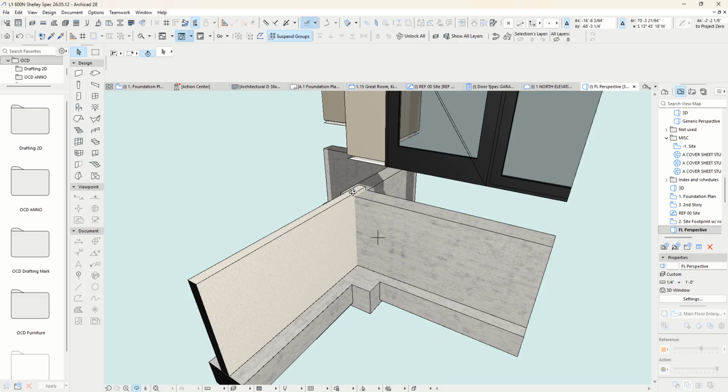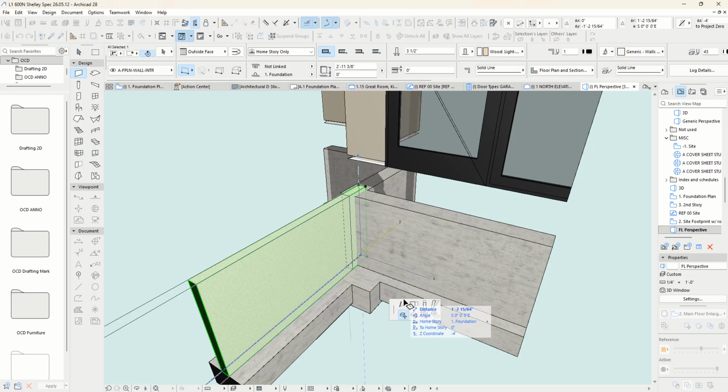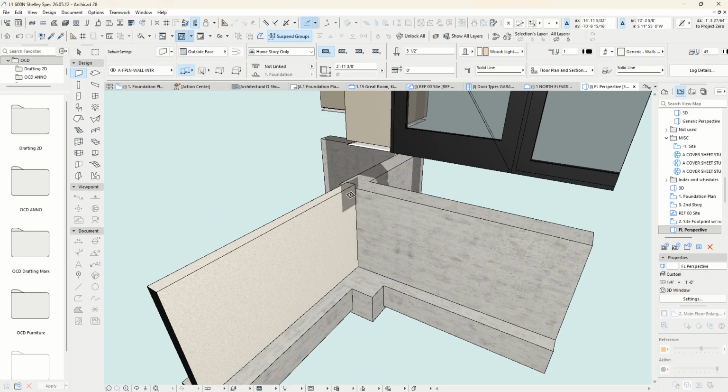But it's just the thing with walls. Sometimes they want to take on their own life and stop where they want to stop and start where they want to start. And it can be challenging. You can use priorities, which sometimes works. A lot of times it doesn't. But moving that back, maybe I'll move it back a 16th of an inch so it just doesn't interfere with that, because this is an interior pony wall. Obviously, it would not intersect that. And so I go to there, and then there it stops. It might automatically intersect later on. I didn't mean to get derailed.